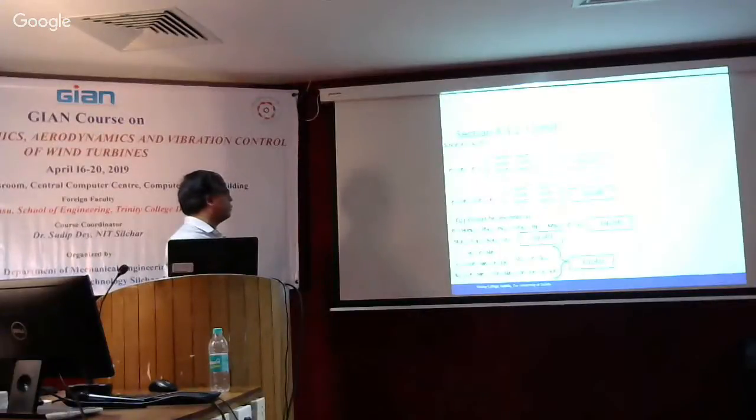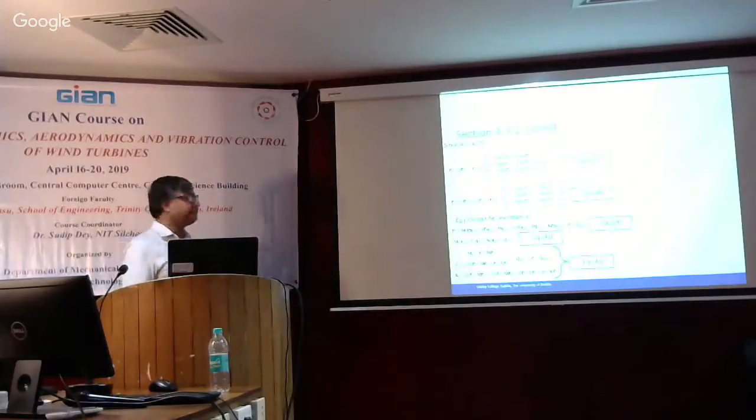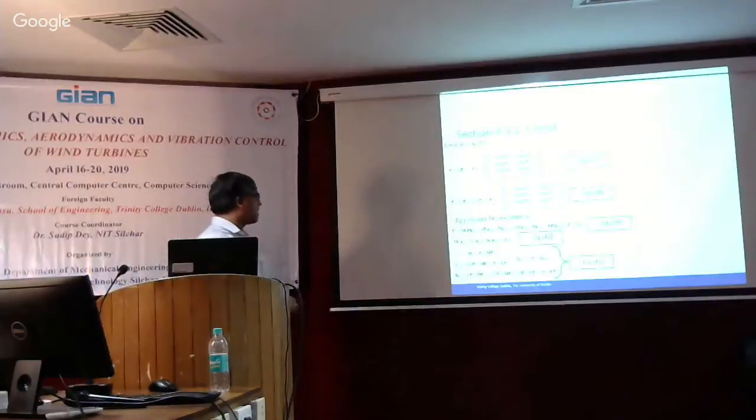Similarly, if we take the q_R dot, there's one term associated with P inverse M P dot, and there's another one associated with C times P. So effectively, we get this matrix here. And similarly with the K, we have a matrix here. But M_C, C_C, K_C become time invariant. The right hand side is the external forcing vector. And the time invariant matrices are now given here.